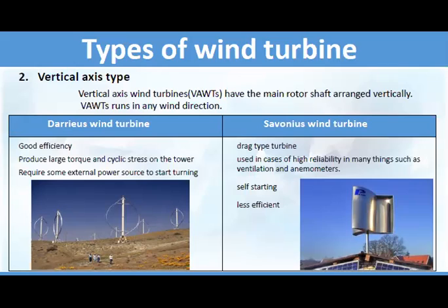The key disadvantages include the relatively low rotational speed, which means high torque and hence high cost of the drivetrain; the inherently lower power coefficient; the 360 degrees rotation of the aerofoil with the wind flow during each cycle and hence highly dynamic loading on the blade; the pulsating torque generated by some rotor designs on the drivetrain; and the difficulty of modeling the wind flow accurately, hence the challenges of analyzing and designing the rotor prior to fabricating a prototype.